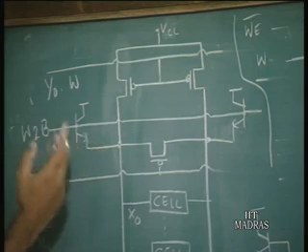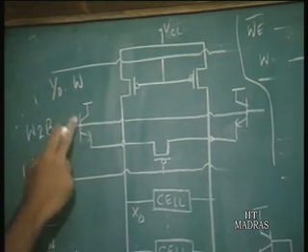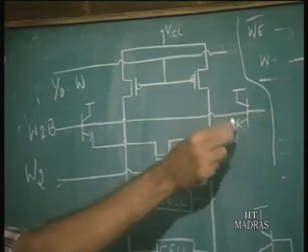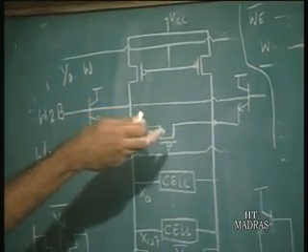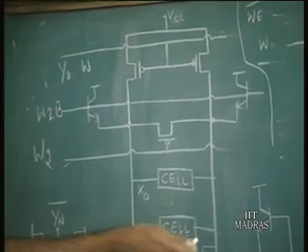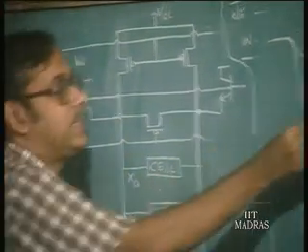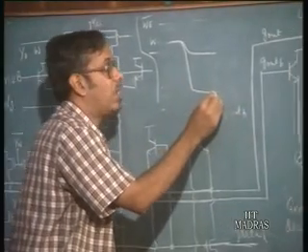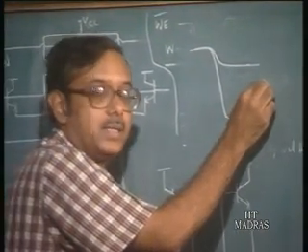Once the write cycle is over, these transistors turn on, and these bipolar transistors help to pull up the data line voltages. So, the voltage here, which had gone low, is going to be pulled up very fast by the use of these bipolar transistors.